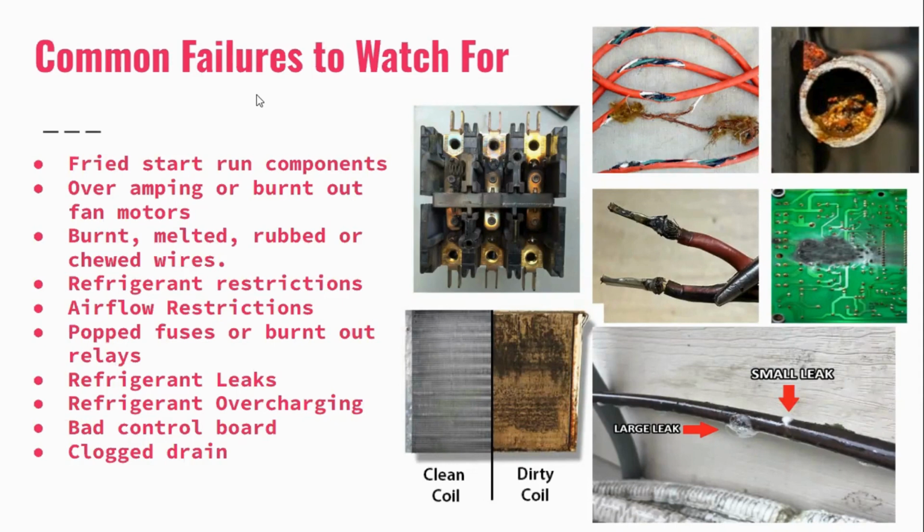So if you come up to the unit and the customer states that they smell something funky when the unit kicks on and then it kicks right back out, you're going to know to go look at your contactor, because contactors like to char. These are the contacts, guys, up here and down here. When this pulls in, these contacts close and touch the other side.